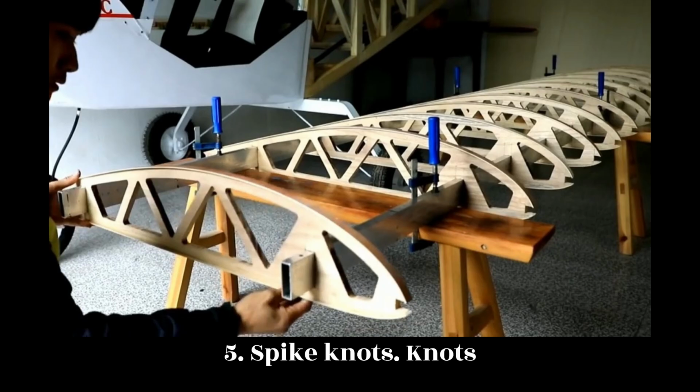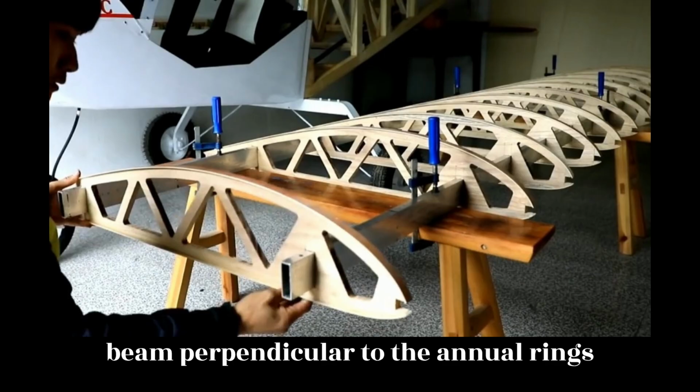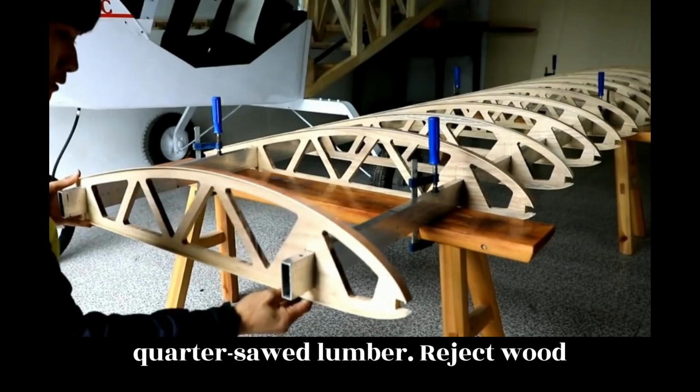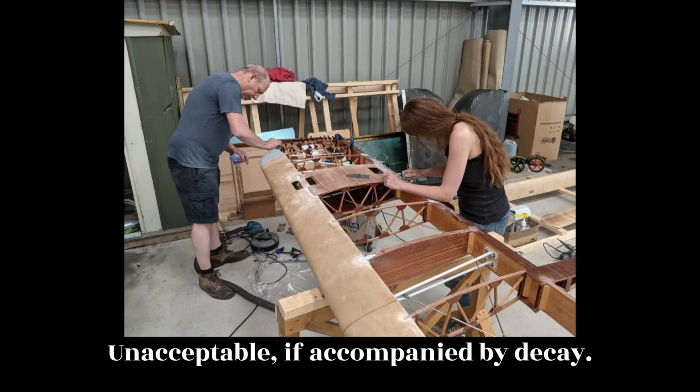5. Spike knots. Knots running completely through the depth of a beam perpendicular to the annual rings and appear most frequently in quarter-sawed lumber. Reject wood containing this defect. 6. Pitch pockets. Unacceptable. 7. Mineral streaks. Unacceptable if accompanied by decay.